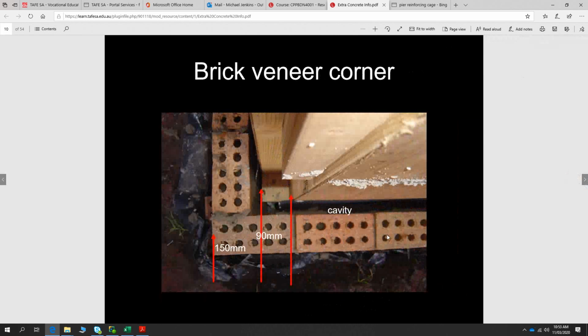You saw with our concrete slab details, with our raft slab details earlier on, that there's a high floor and then there's a set down. That set down is for this brickwork. So the brickwork sits within that set down. Typically you have a 76mm set down, which is the height of a brick. Then you have a cavity between the brickwork, and then you have the wall framing in there.